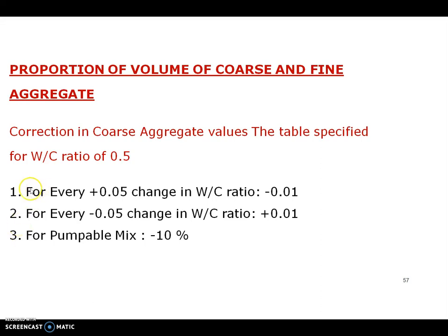Here, for every 0.05 increase in the water cement ratio, the value changes by 0.01 decrease, or for every 0.05 decrease in water cement ratio, it increases by 0.01. And for the pumpable concrete, this value should be reduced by 10%.